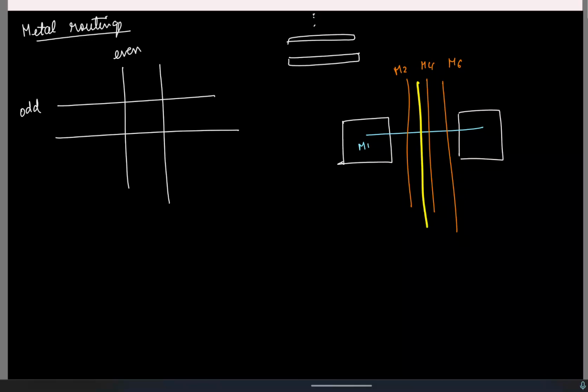So that way you don't run into the issue of, sorry, this ensures that 2 wires, 2 contacts don't touch. Basically, if you don't follow it, you could have a possibility where one of the routings is also in metal 1. Then this will get shorted, right? So basically, you will have something like this and something like this, and how to draw 3D. That will get shorted, but that's not what you want. If you follow this, you can be assured that there will be no similar metal connections happening in the other dimension. So you can make all the connections without any worry.